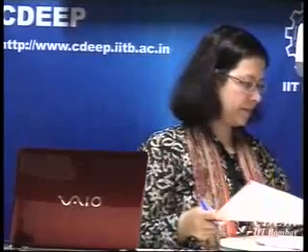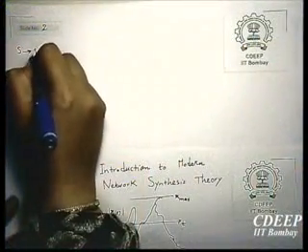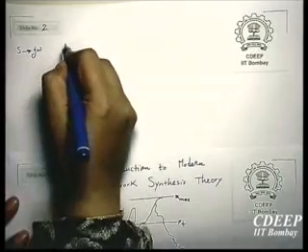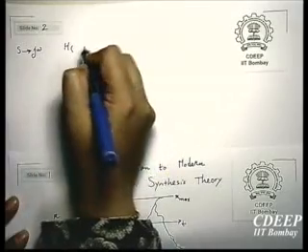Okay, so therefore now we have this noise, and then now we have a low pass filter, completely passive filter, and we think it is an ideal filter, therefore we can apply any signal. Now we need to see what are limitations on simple RC filter. So now we convert S to j omega, and we will go to the j imaginary axis only.